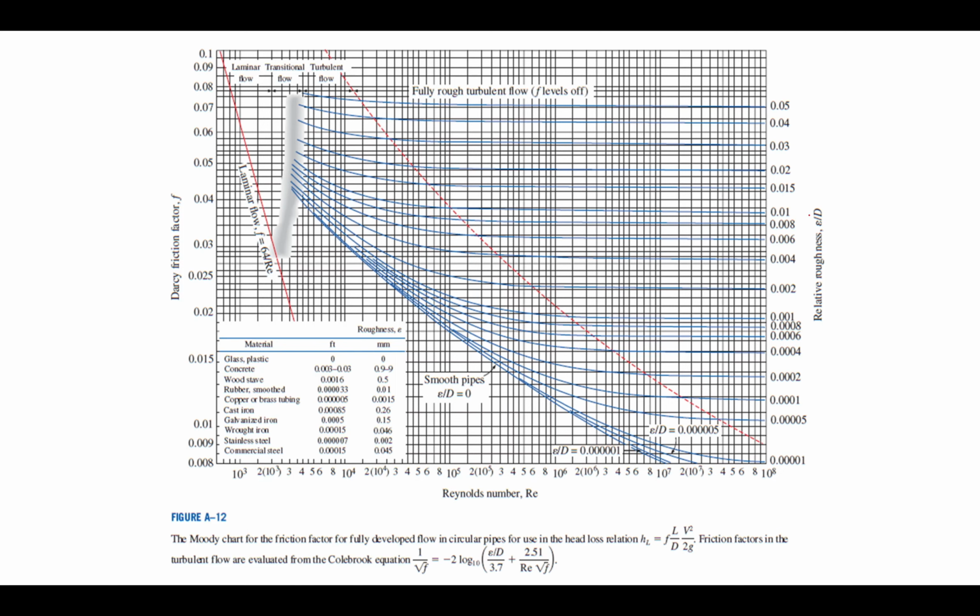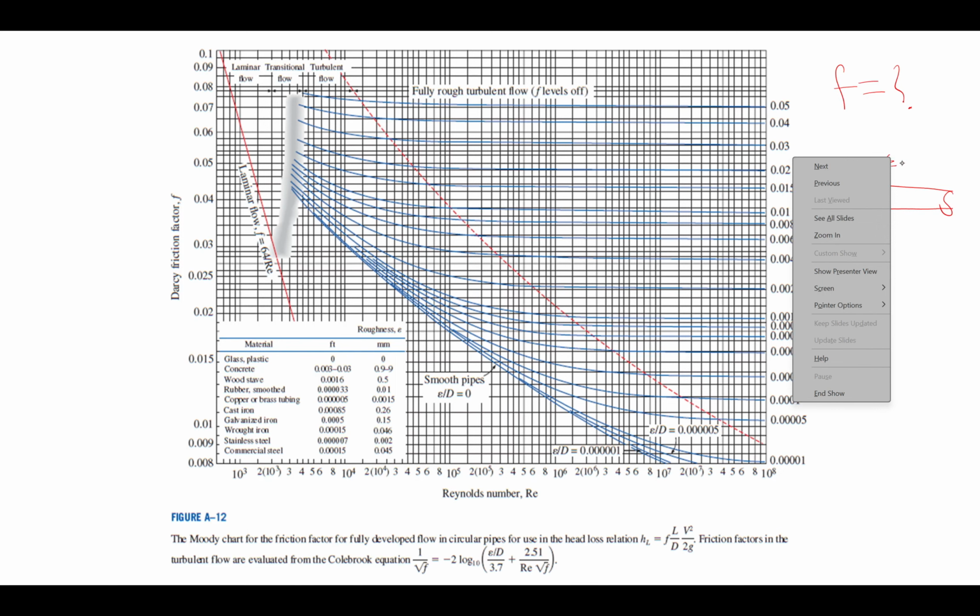What we have discussed here, actually this Moody diagram is for what? Calculating the roughness value, that is the friction factor for turbulent flow. So what is the value of the friction factor in turbulent flow? Let us take an example in the fully rough region. If your pipe is like that and your epsilon by D value is 0.006, so this is the 0.006 line.